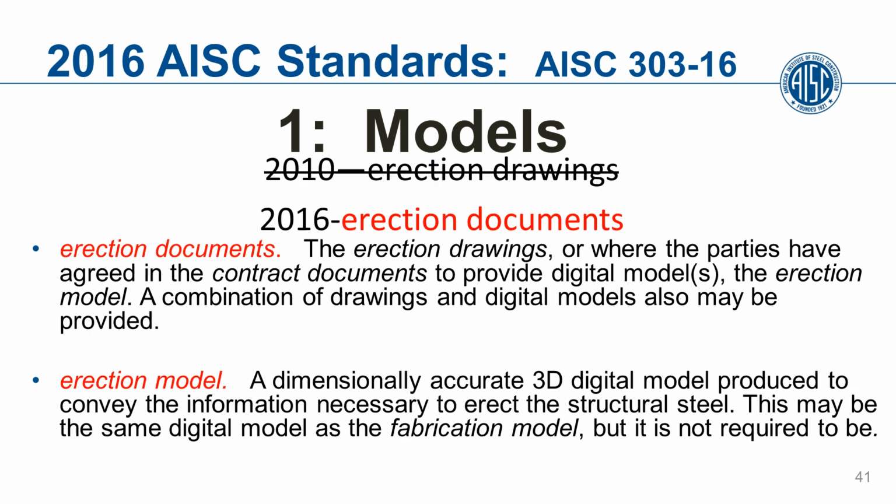Erection drawings has been replaced with erection documents. And you look at these definitions, they match what we just talked about previously. The erection documents is either the erection drawings or it can be an erection model or a combination of either one. And the erection model, again, can be the same as the fabrication model, but doesn't need to be the same. We're giving flexibility contractually of whatever you would like to do.